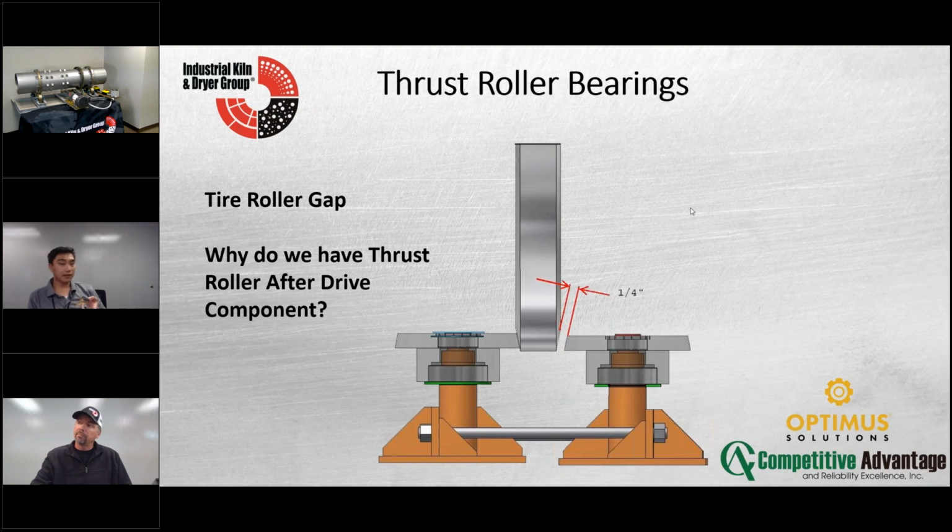You've got a thrust roller that could pop off. You've got other wear on the support rollers, your pads, your retainers. Something so small as that can cause a lot of issues. And again, guys, this one could be catastrophic, because we've seen it. Or it's another one of those things that over time you'll end up with problems, and that's the harder one, because you won't know it's a problem until 6 months or a year from now.